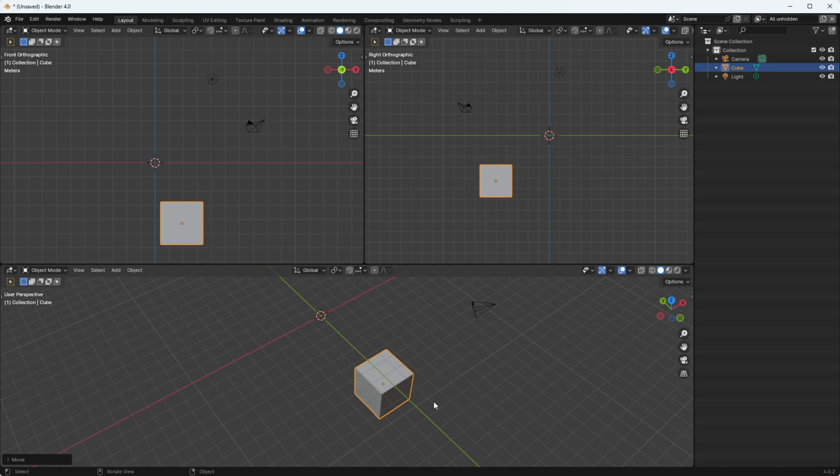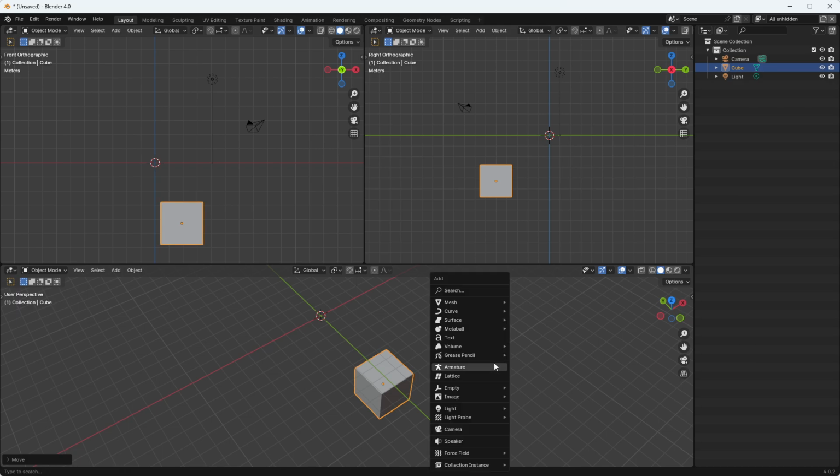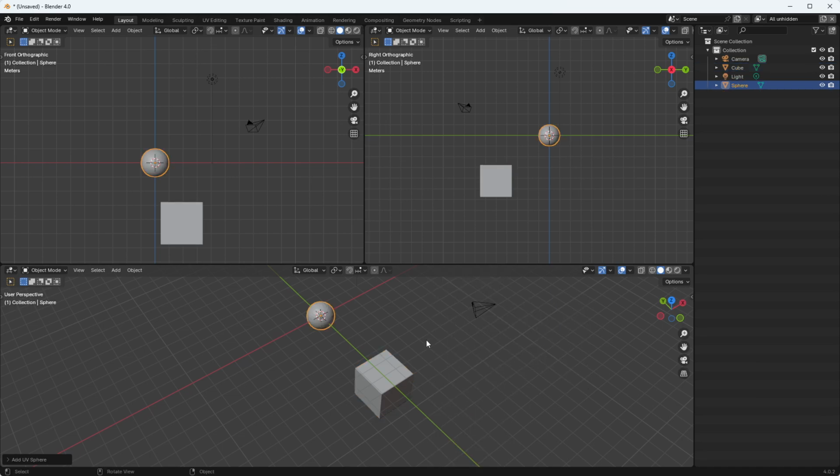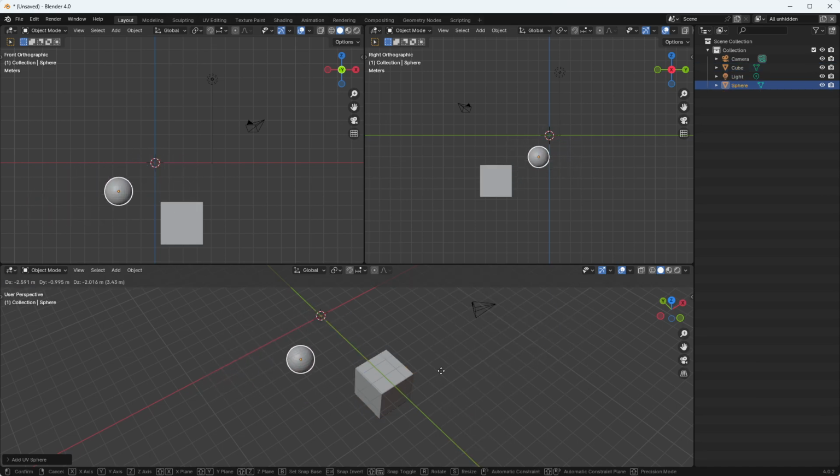And then to add objects, you hold down the left Shift with your pinky, and then use your ring finger to tap A, and it pulls up this dialog, and it's the add dialog. So I can go to add mesh, and meshes are what you're mostly going to use. And I added a UV sphere, and I can press G and move it around however I want.